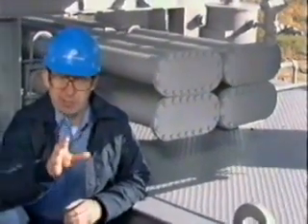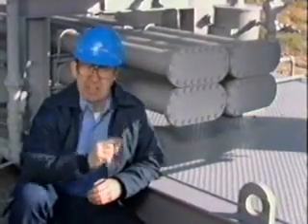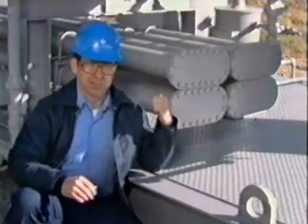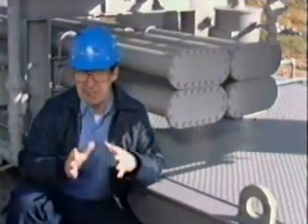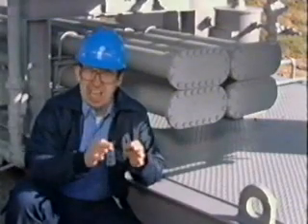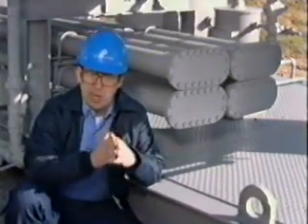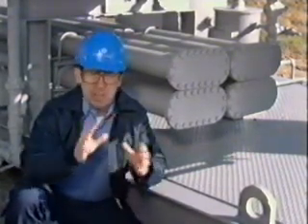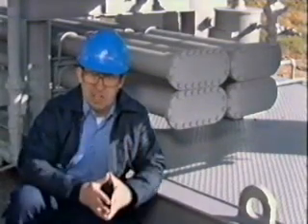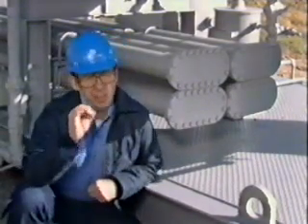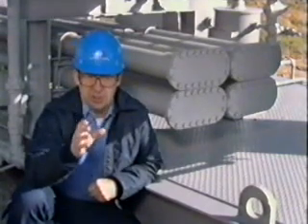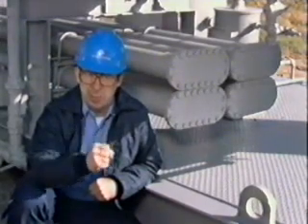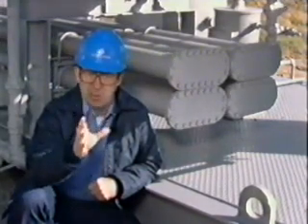There are two types of heat exchangers used to cool the glycol in a glycol dehydration unit: glycol to glycol heat exchangers, like these, and a glycol to gas heat exchanger. Lean glycol leaving the surge tank must be cooled prior to entering the contactor. The cooling allows the lean glycol to absorb the maximum quantity of water from the gas in the contactor. The heat exchangers are very important in the overall operating efficiency of the dehydration unit. They substantially reduce the amount of heat required by the reboiler and allow maximum gas drying in the contactor.